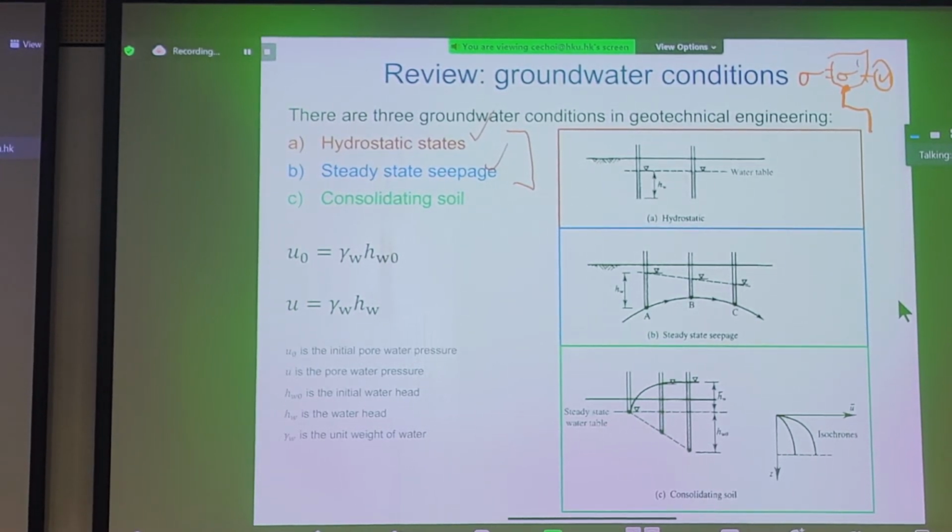But in geotechnical engineering, sometimes it's not so clear cut. We don't know the pore pressures because excess pore pressures have not dissipated due to rapid loading, rapid construction. So under those circumstances, we're forced to check effective stress conditions and total stress conditions. Effective stress parameters for strength are phi dash, c dash; total stress parameters are cu or su. So bear that in mind if you're not quite sure when to use effective stress or total stress.